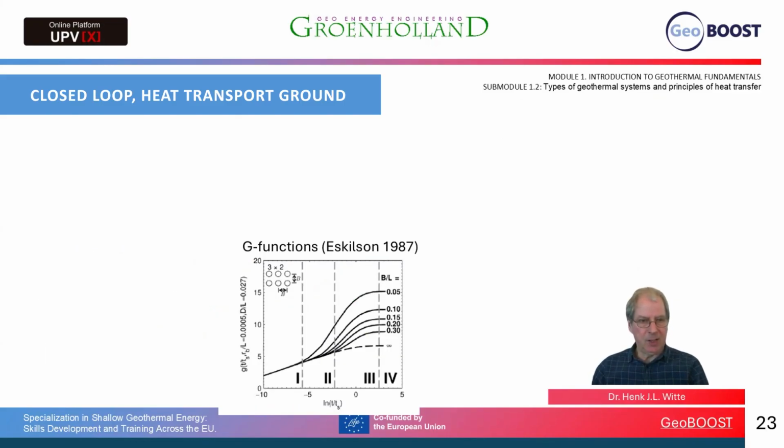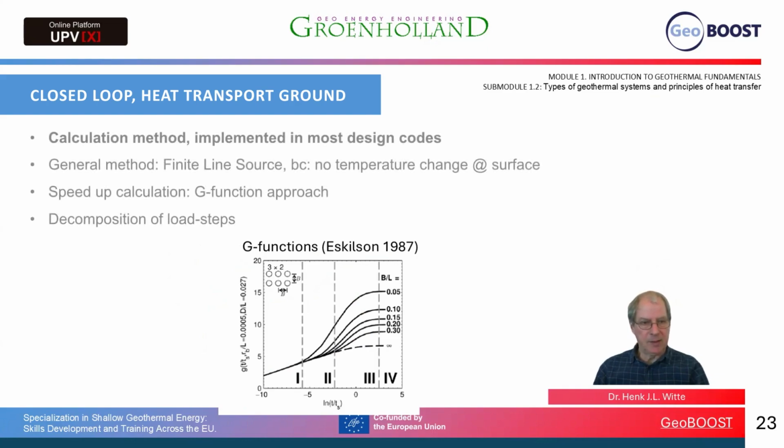This was all developed in the 80s, especially in Sweden. This is from a PhD thesis from Eskilsson, 1987. And this calculation method is implemented in most design codes. The basic method is the finite line source.